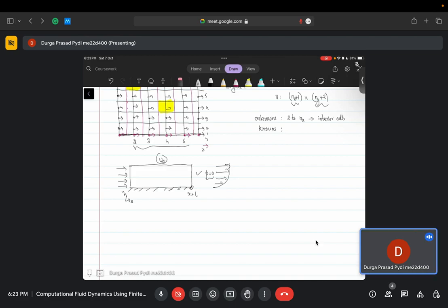Yeah, so this is something that you will always be facing in CFD. You need to come up with some boundary condition for your domain. Whenever you fix your domain, you need to give all the boundary conditions. The advantage here, even when you are using an upwind scheme, is that all these values will depend only on the previous nodes. So you don't have to really know the boundary values. If you assume a high Peclet number, if Pe tends to infinity, then there won't be any diffusion term. So to determine the values at the boundary, you need to just know the previous interior cell values. You don't need to know the east boundary if flow is along the positive direction.